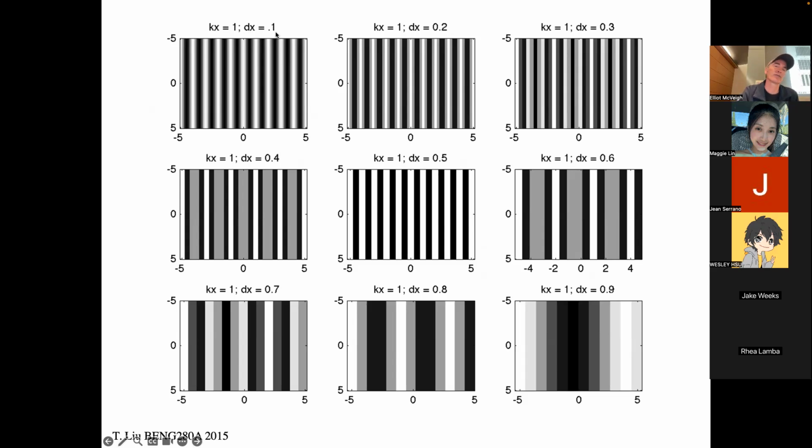We're going to sample it every 10th of a centimeter. And so we'll get 10 pixels across each 2 pi phase of the sine waves. And this is what the picture looks like. So it looks like a nice plane wave, right? If we drop every other sample, so now we're going to sample that sine wave at 0.2 centimeter intervals, right? So I'm going to get 5 samples per wavelength. This function is what we get. And you look at it, you go, huh, it's sort of got a very discrete, steppy kind of look to it, but it's still a good representation of that sine wave, right?